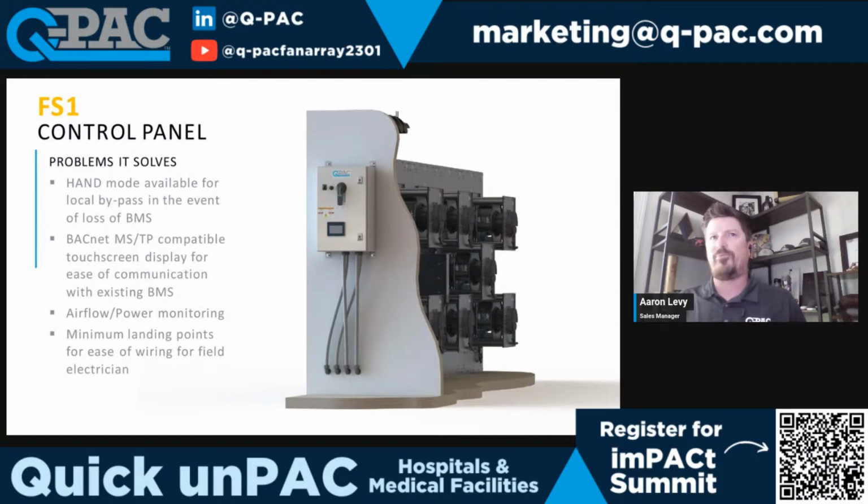And for our premium systems, we do BACnet MSTP. Right now, we don't have an IP version available. I believe it is something on our roadmap that we're working on and that we would probably see in the not too distant future. But for the most part, MSTP does cover a large portion of all the solutions that we run across. Again, you get airflow and power monitoring right there locally through that 7-inch Schneider touchscreen display on the premium controls. And again, minimum landing points.